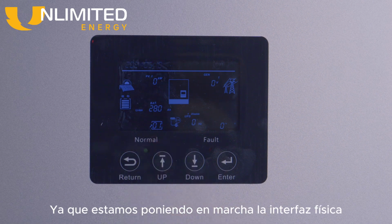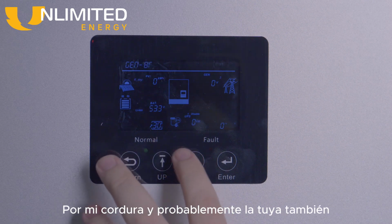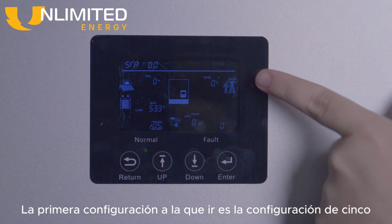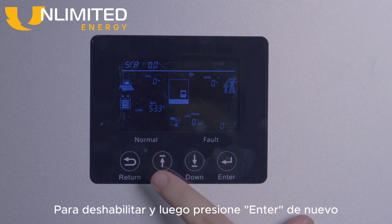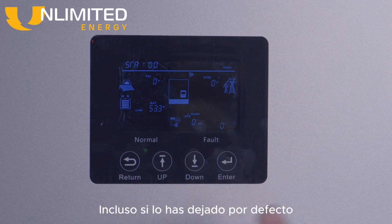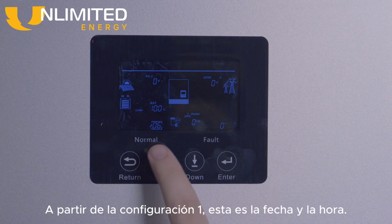Since we're commissioning on the physical interface, we're going to turn off the buzzer during the process for my sanity's sake, and likely yours as well. The first setting to go to is setting 5. Press enter once on the setting and down to change to disable, then press enter again. All of the settings can be changed this way, but some will restart the inverter even if you've left it to default. Next, we're going to go in order starting from setting 1.